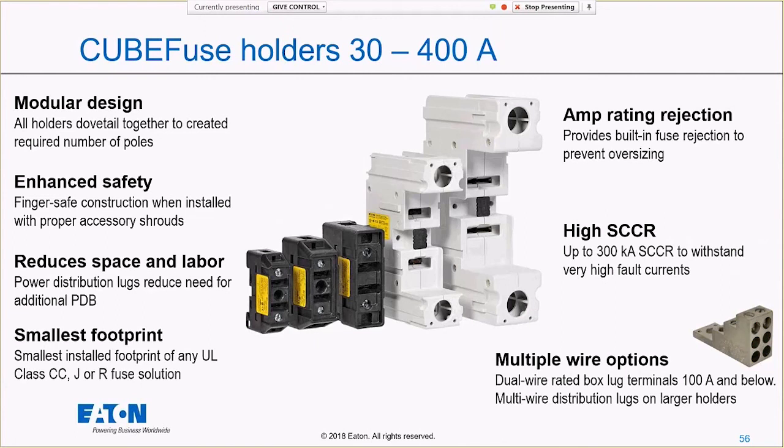And one thing I always hear about finger safe covers for fuse holders is that, right, you ship it out with the covers and it's perfect. And the first time someone takes those covers off to work on the machine, they never get reinstalled, right? They wind up in the bottom of the panel. They wind up thrown out. Those finger safe covers don't always get reinstalled, but these are going to be finger safe inherently, right? So if the fuse is in there, you're going to have that finger safe construction. So really, really great product for that reason.